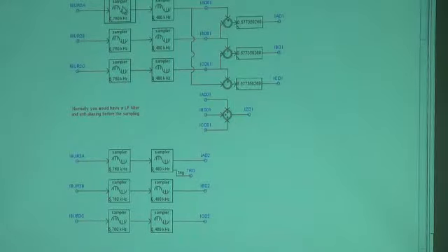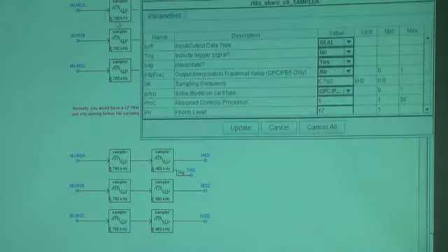Analog signal sampling, we have these components called the sampler. So essentially we feed in the 50 microsecond signal, and then this sampler, you specify the frequency, and it downsamples. It also can do interpolation.